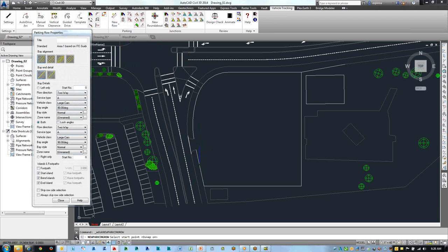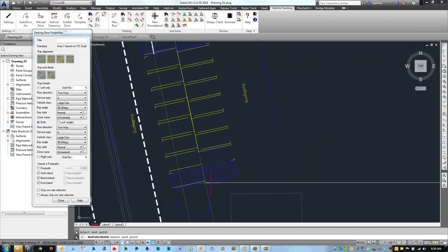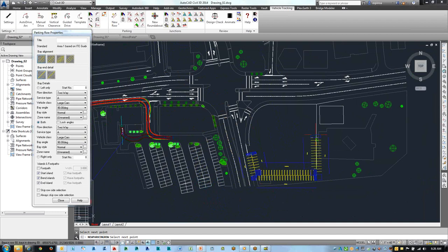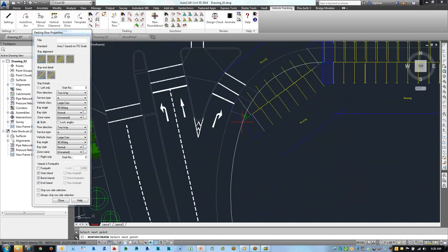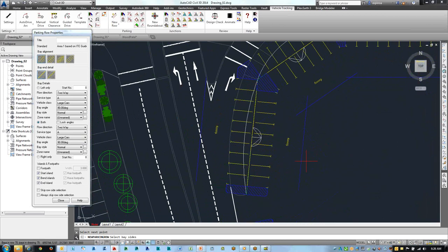And I'll turn on my O-snap here, and I'm going to snap to the outer perimeter of this parking design. And noticing that there are, in fact, curves. There's a compound curve in the site of the stalls, of the lot itself. So I'm going to go ahead and pick the next endpoint here. Let's pick that endpoint there, and then this endpoint here, and this endpoint here, that endpoint there. Going to the endpoints of these curves, that's one curve, and then we have the compound curvature down here to the end of the other one. And I'm going to go ahead and hit return.